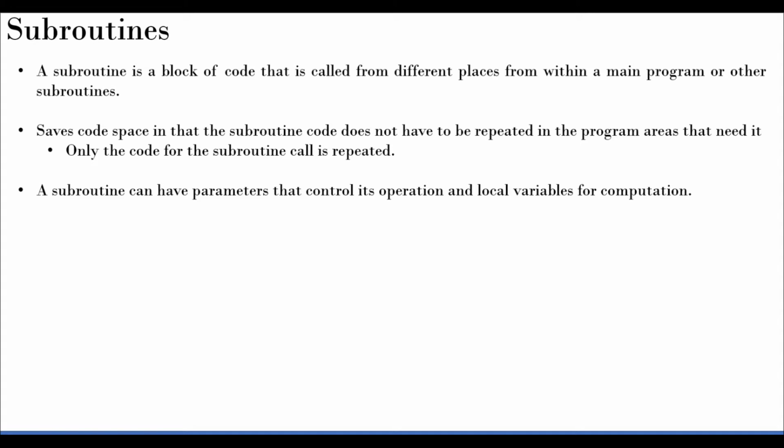Here also we will understand that concept very clearly in this section, where it's important that you are careful, because please understand that when you write a C program or MATLAB or Python, you are working at a very high level, right? But when you write programs in assembly language, you are really working at the register level. That's the lowest level that you could think of. Now just imagine that you're changing a register. You have some value in a register in the main function, and then you entered a subroutine, and inside that subroutine you accidentally change that register value. Then what's going to happen is, when it returns back to the main function, that value in the register is already changed. So that's very, very important. There's a way out, actually, and I will explain how to go about it.